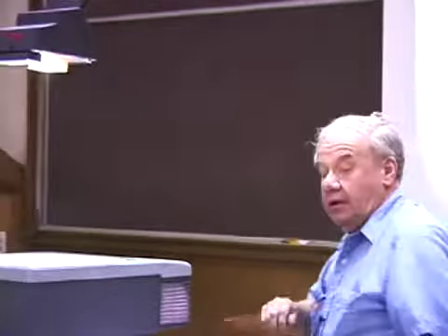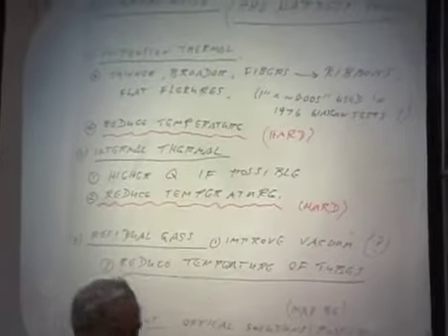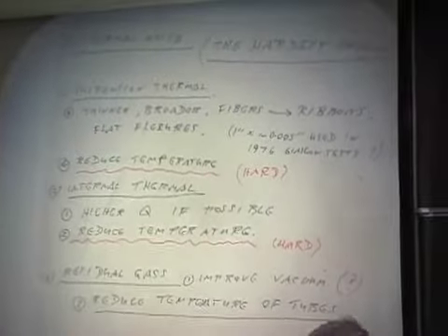Okay, thermal noise is really the tough one, because what can you do? Well, first of all, suspension thermal noise, there are many ways you can see to improve that. We're using quartz fibers, which is pretty good stuff for it, but you could think of all kinds of ways. For example, you can't make the fibers really thinner in cross-section because they're already highly stressed near the breaking point, but you can flatten them so that they bend more easily in one direction, so use ribbons.